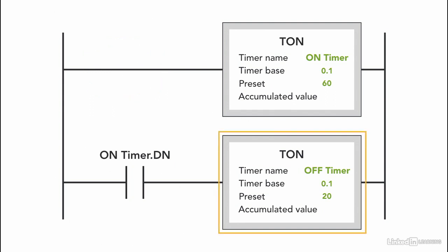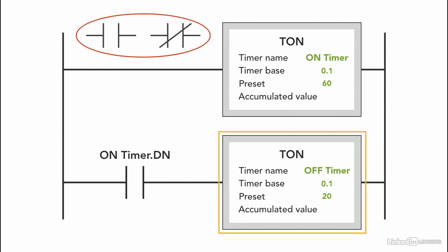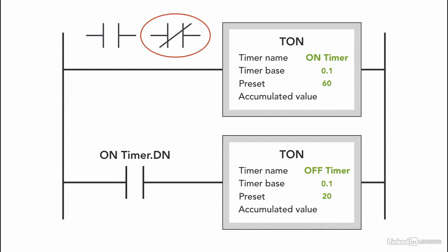So now we need to think about how to make the rung go from false to true, and at the same time ensuring that the timer increments to the preset value. So we can take advantage of the second timer by using the timer done bit. Now think about either using XIC or XIO instruction. Let's see how the program works when using XIO instruction.